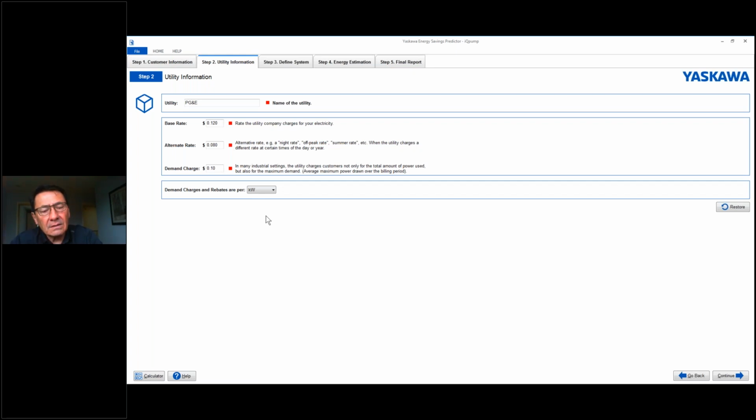Note that very few installations I've been at have had a power factor of 0.9 and above on a VFD, unless the VFD has harmonic distortion, either filtration or active front end, such as the Yaskawa matrix drive. As a point of reference, the Yaskawa matrix drive has a power factor, in other words, its energy usage efficiency, of 0.97 or better, so better than 97%. And that's because its input harmonics are so low. But that's a subject for a different class.